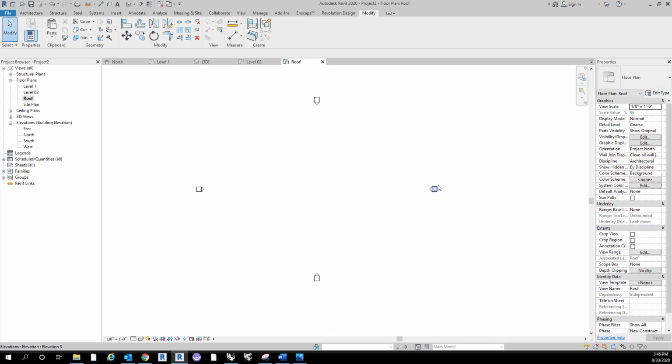All right, and then what I'm going to do now is go to roof, and I'm basically going to trace the outline of that floor, but I'm going to create it using a roof tool. The interesting thing about Revit is it allows you to control the depth of the view that you're in. Let's say I'm on level 3 and I actually want to see the site and the ground plane. I can adjust the view parameters so that I can extend the view all the way down to the ground so I can see the detail.